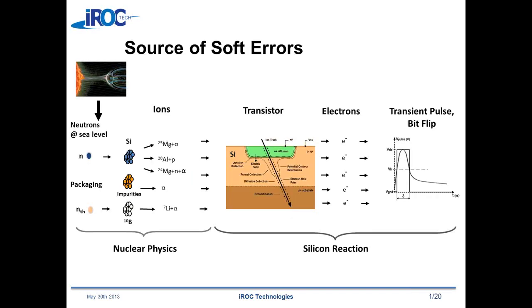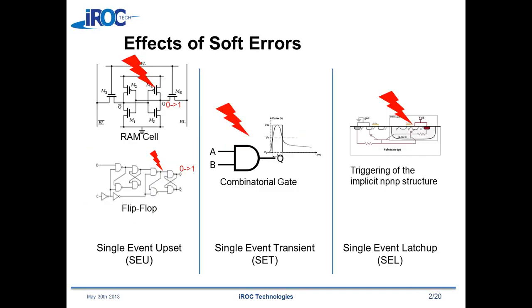Hi, Paul. Sure. Let's start with a little overview of what actually causes a soft error. A soft error is triggered by a subatomic event that could either be a neutron or an alpha that's emitted from packaging materials. If it's a neutron, then the neutron has to hit the nucleus of an atom in the chip, typically a silicon atom, and cause charge to get deposited around a transistor. When that charge gets deposited, it can create a voltage spike, and that can cause a soft error effect.